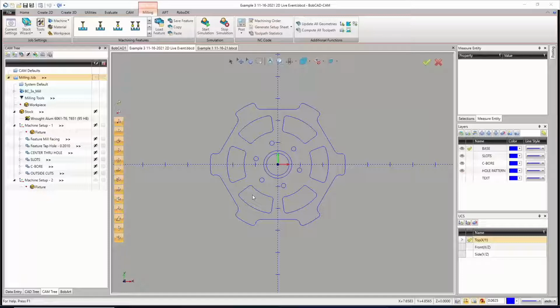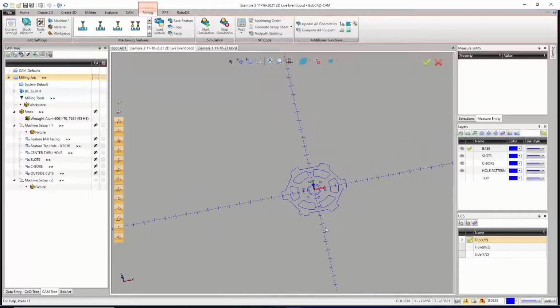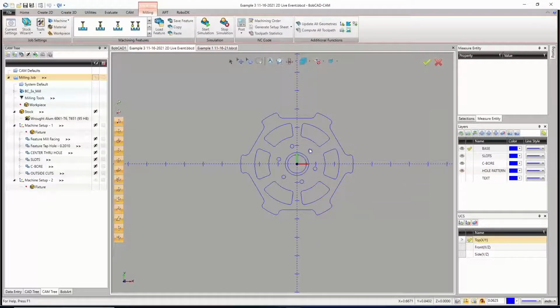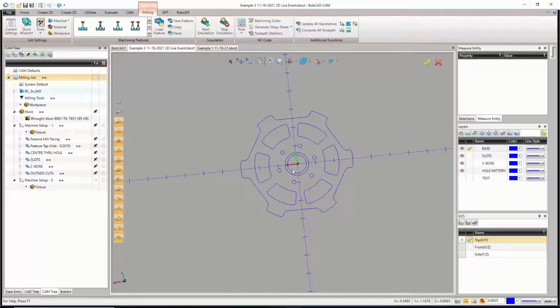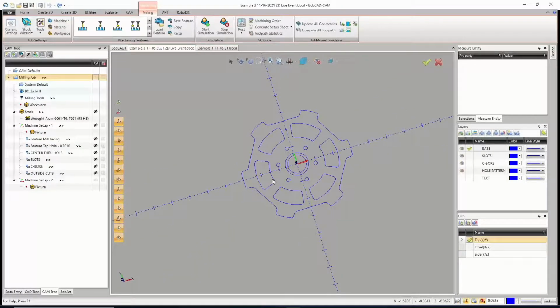But we have to make sure, especially if we needed to drill the holes in that specific location, that when we flip our part over, we flip it the same way at the machine later on, especially with that hole pattern being off. Because if I rotate across the Y-axis, the hole switches spots. So it's just knowing which way you did it. Really, it's not that important.